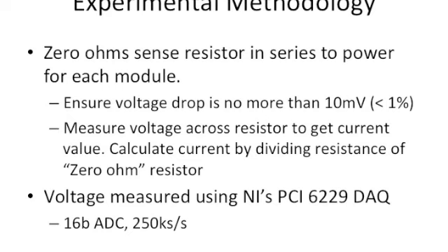Current measurement is trickier, because to measure current you have to put an ammeter in series. So how is that done? Well, one way it is done, what these guys did, was put a very small resistance in series to that component. They call it a 0 ohm resistor, but it's not really 0 ohms, it will be a very small number. Maybe an ohm or something.